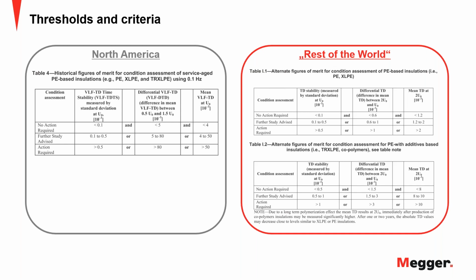In general, you can say that with PD testing, anything that is relevant, that is really a defect, will show up in hundreds and thousands of picocoulomb on your detector, on your test system. But at the end of the day, you have to come up with your own risk management matrix and decision-making matrix. I showed you this one example from one German utility.